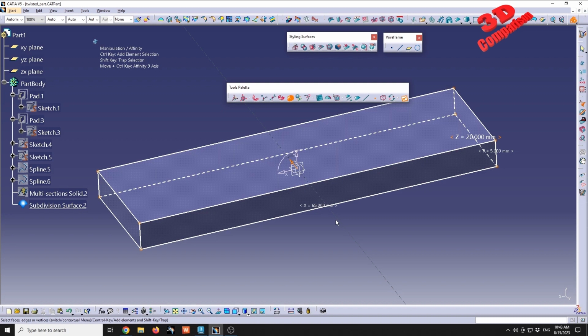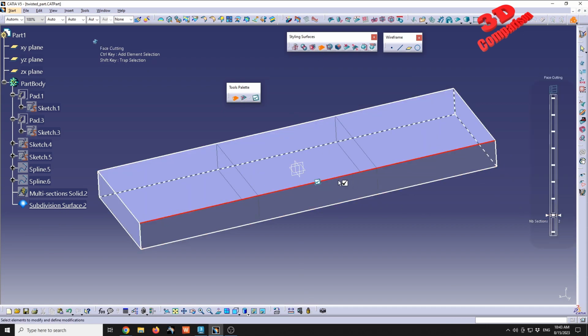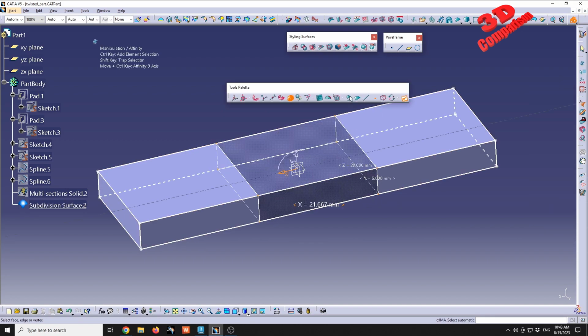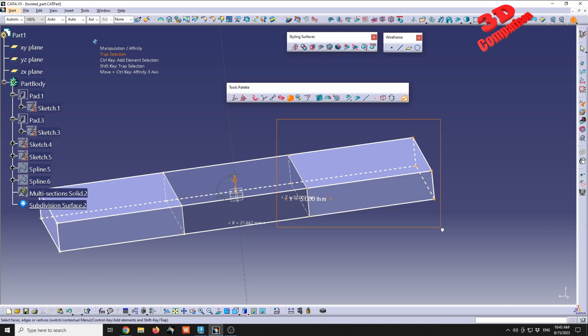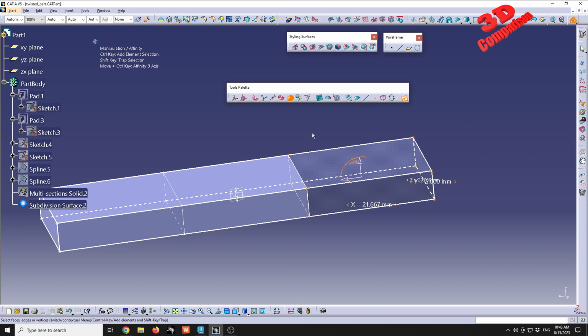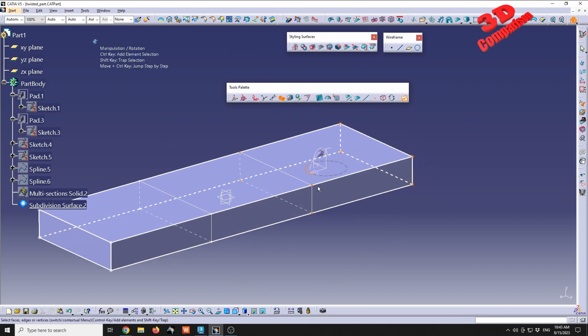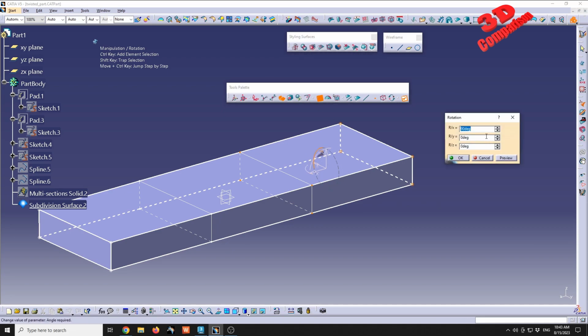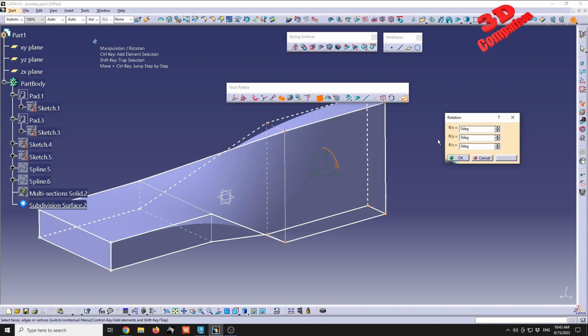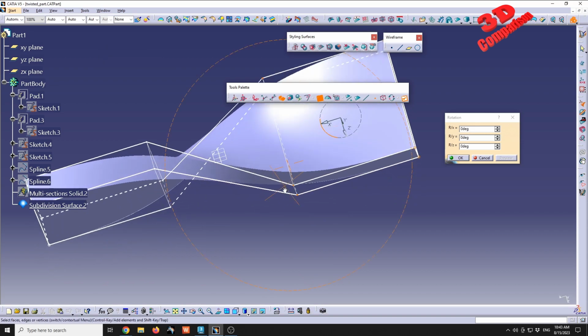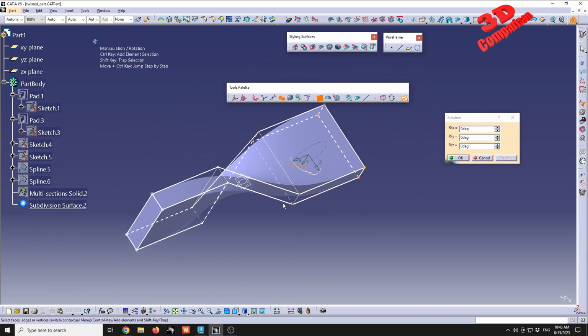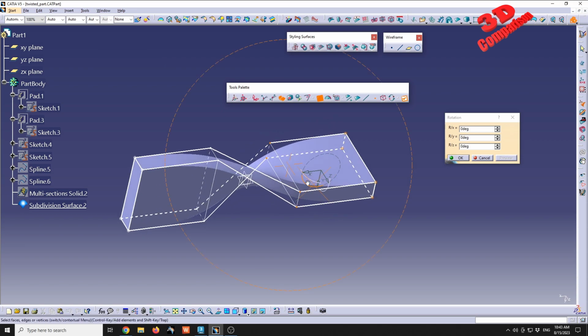Now, in order to twist it like that, I will have to cut the face. So I will go with face cutting with 2 cuts. And now, if I select only a side, like this, by holding down Shift, I will do a big trap to get all those 8 points. I will go to the rotation, and we're going to see that rotation axis. This will be 90 on X, and if I go with 0, I will have that one twisted, let's say, embedded within the part.